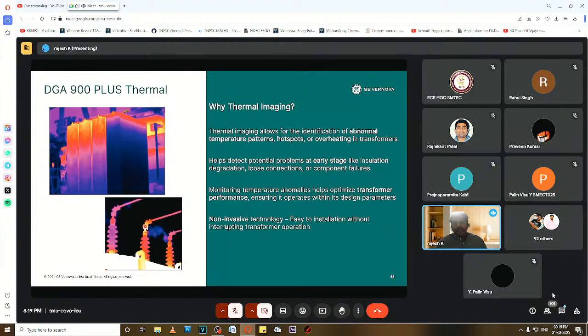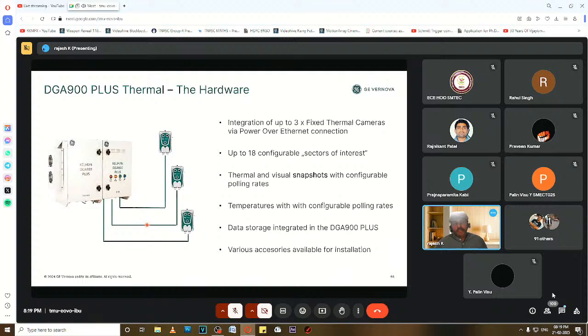Okay, so these sensors will help us to really identify and act immediately, because this transformer would have gone for maintenance a week back. But what we would see, because of some small loose connections, like in our house, if you have a loose connection in your switch, of course the switch will burn out and it will have an arcing and it will fail, maybe a new switch. Okay, so it can happen anywhere. It's not necessarily new or old. That's why condition based maintenance and alarms will help us. Even a premature infant stage failure can be avoided here.